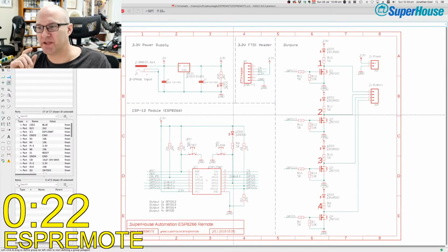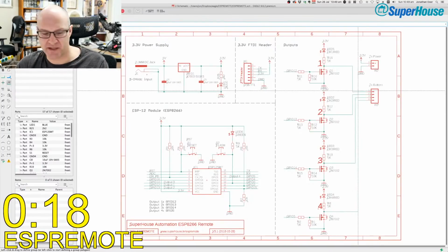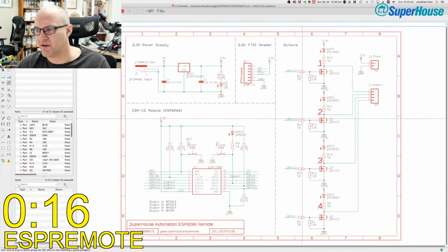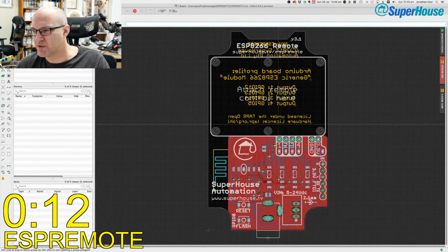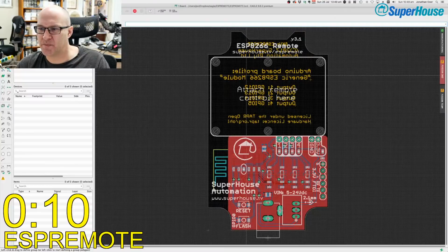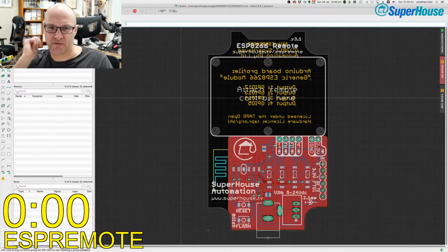It does vary, but most of them are like that. So what you can do is simply connect to ground and one side of the button, and then by firing one of these MOSFETs you can trigger the remote control. So what you do is cable tie the remote control PCB into the blank space of the PCB right here, and then patch wires down to these 1, 2, 3, 4 connections, and then you've got an MQTT Wi-Fi connected remote control.